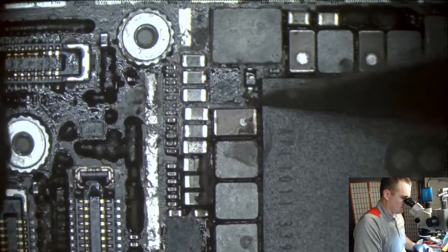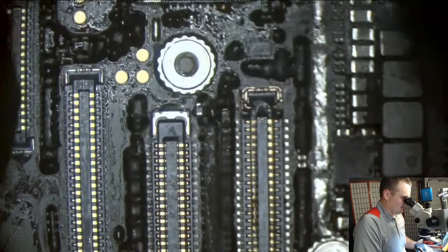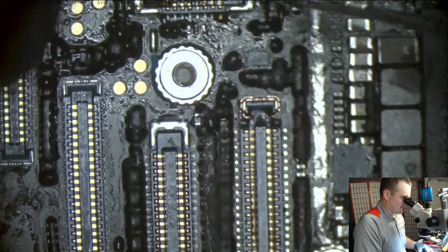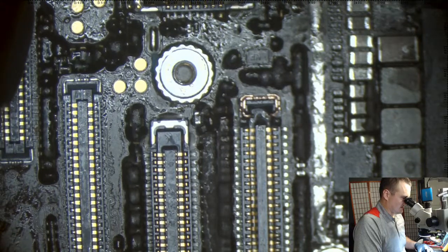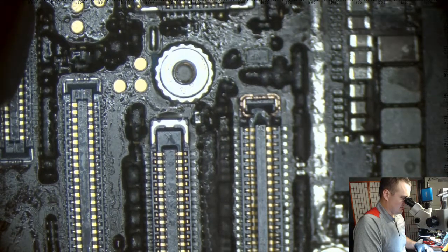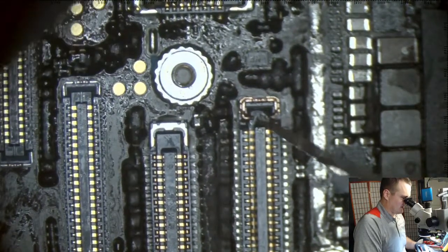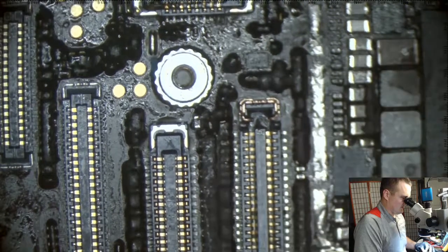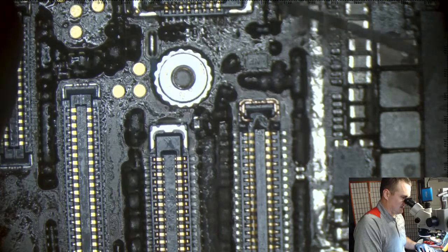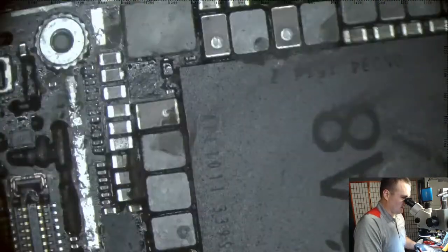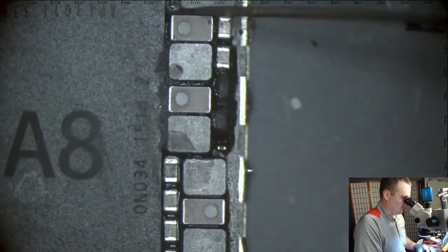Also, get all these little tags out here. I'm probably gonna dip this top half in the ultrasonic cleaner once we're satisfied it's been repaired. Stuff like this, once that flux gets enough hot air on it, it really turns into a glue. Makes it hard to plug in connectors. All these fluxes say no clean. That's not true. You should clean your flux. Don't leave it on there. It will corrode.